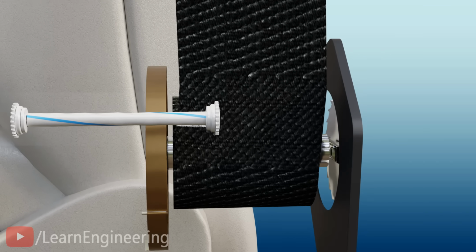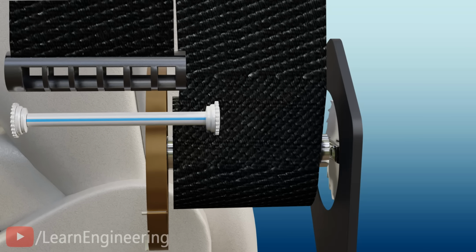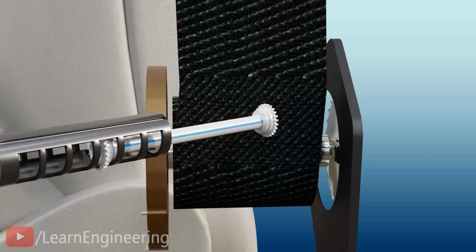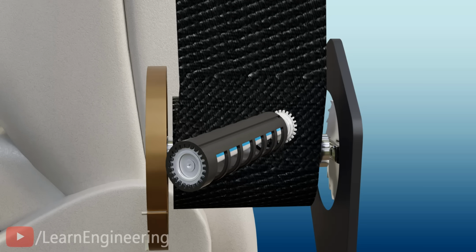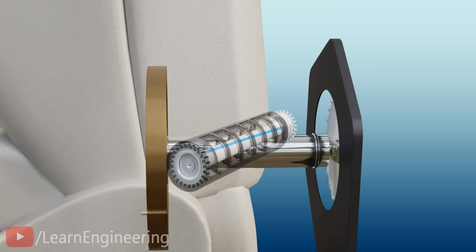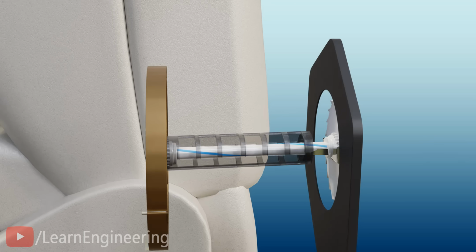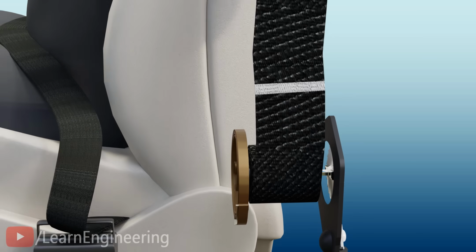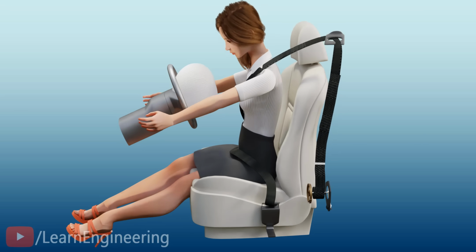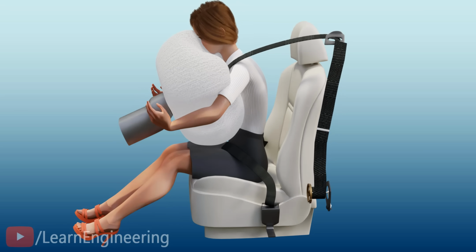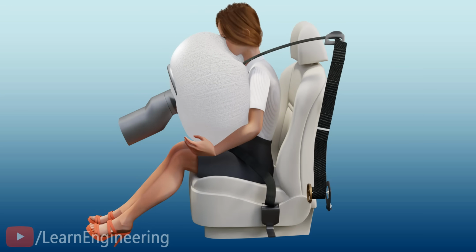To overcome this issue, the belt webbing is connected to a spindle, and the spindle is connected to the free end of the torsion bar. This connection means that during torsion, the whole spindle will turn the maximum twist angle of the torsion bar. This unit replaces the normal shaft of the retractor. This way, the belt will be released a little when the belt pressure reaches a critical value, which saves the passenger from internal organ injury.